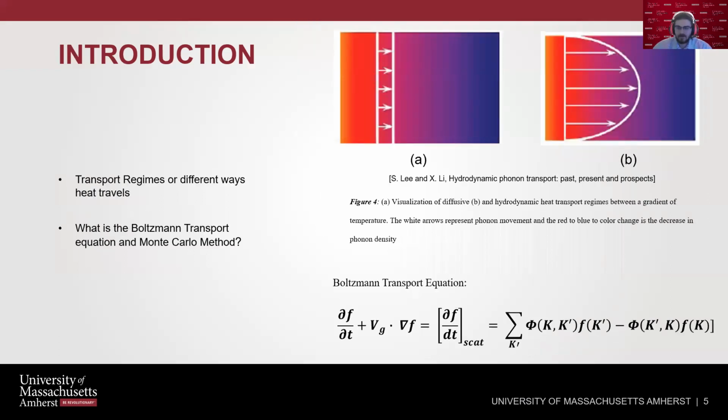The goal for many researchers is to have N-scattering be the dominant scattering mechanism inside of a material as it causes the least thermal resistance. This, however, is difficult to achieve as N-scattering is relatively weak compared to U-scattering. N-scattering and U-scattering influence thermal transport in different ways, relating to three regimes of transport: ballistic, diffusive, and hydrodynamic. For this research, we focus on the diffusive and hydrodynamic regimes.